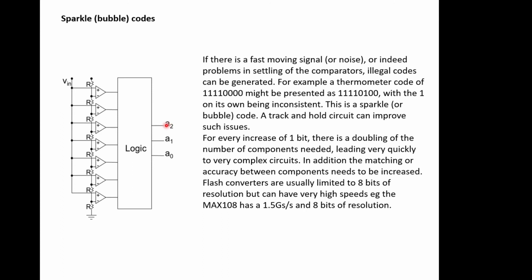1.5 gigahertz is going on here, and you've got to read that data out and do something with it in that time period. So you've got huge amounts of data flying out of this thing, and you haven't got very long to do anything with it. So you might even struggle to store it onto any memory unit. So you've got to be selective about what level of performance you really need, because not only does this have to be high performance, but anything you connect it to also has to be high performance as well.